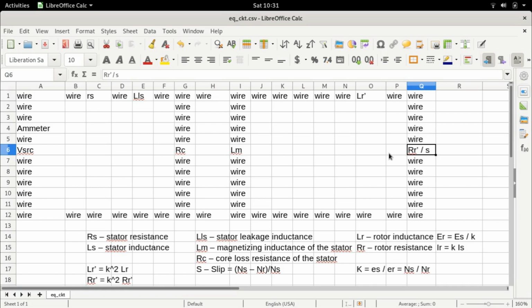So the only load on the rotor is the rotor inertia itself, which is very low, because typically a motor is designed to perform a certain task, it could be a pump or something else. That load is usually the significant part. The inertia of the rotor is usually much lesser than that of the load. So at no load test, we assume that the slip is almost close to zero, and therefore this branch is open circuited. This leaves only this branch.